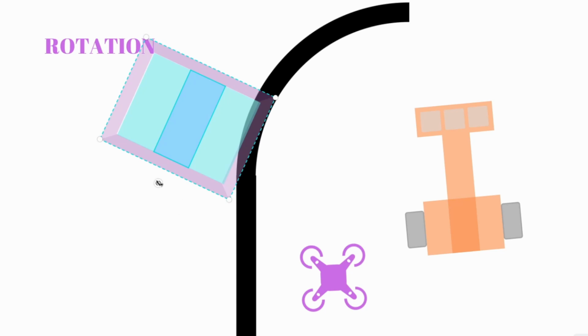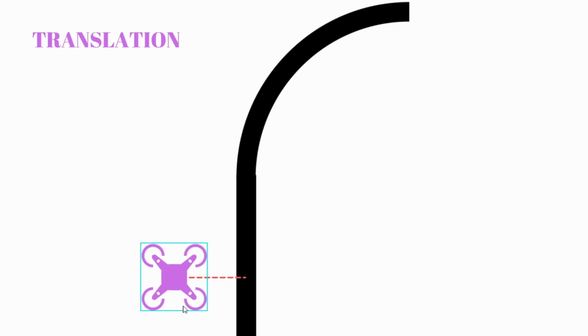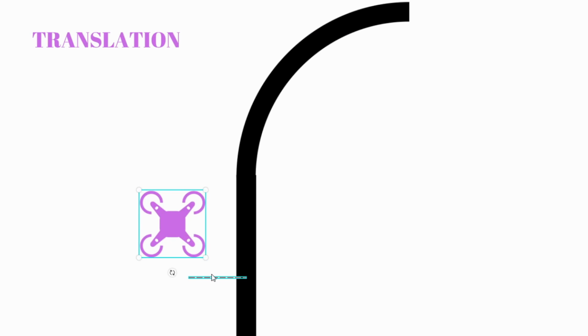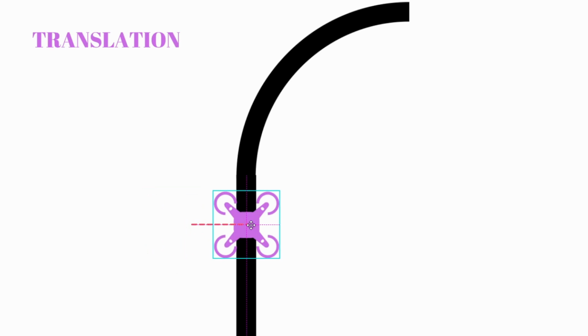So we also have the problem of translation. So this is the idea of translation, that when the drone is moving, at any given point, we will try to find the center of our black line and where the drone is. So if the image or the line detected is right in the center, we will keep going forward.